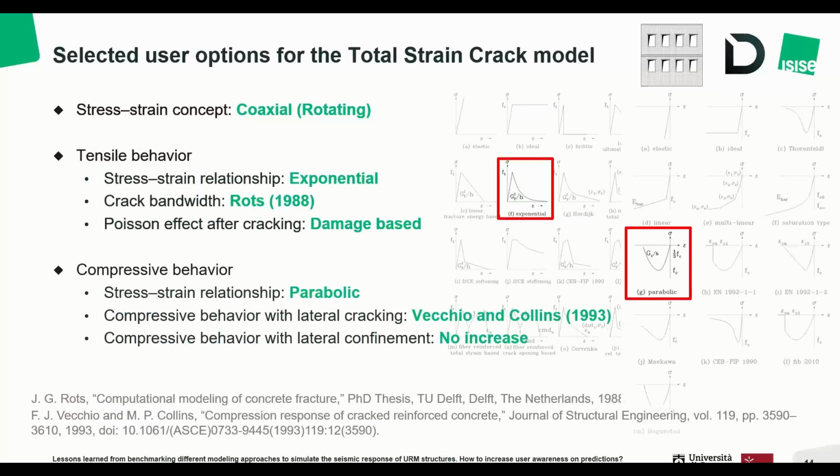In terms of compressive behavior, I selected the parabolic relationship, and another important option, which is the compressive behavior with lateral cracking, for which I selected the model by Vecchio and Collins in 1993.